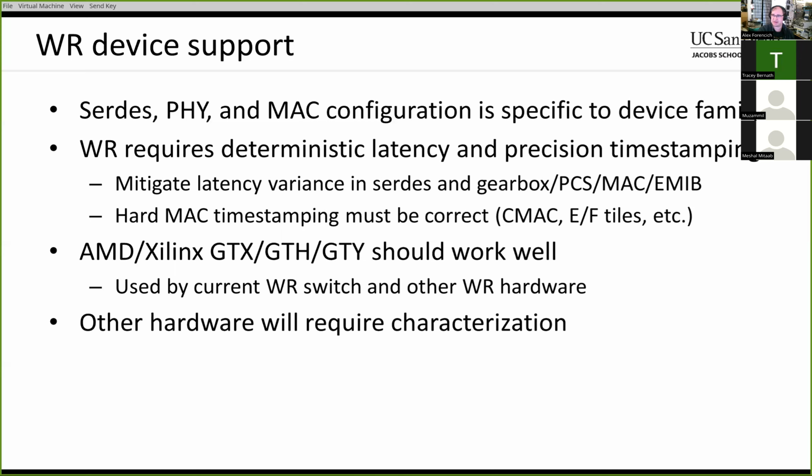The SerDes, PHY, and MAC configuration is going to be very specific to the device family. Whenever you have integrated serializers, there's a question of whether they're going to be deterministic enough to support White Rabbit. But within one device family, presumably all the performance is going to be the same. So you don't have to test every individual chip, but more like every FPGA series, like the Xilinx UltraScale Plus series or the Intel Stratix 10 series, for example.